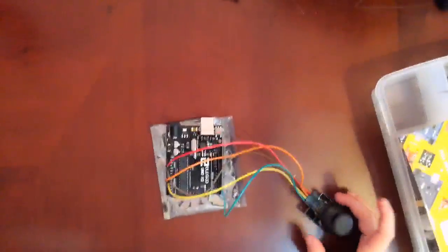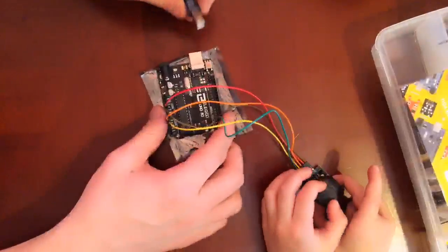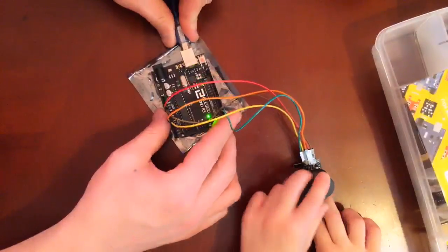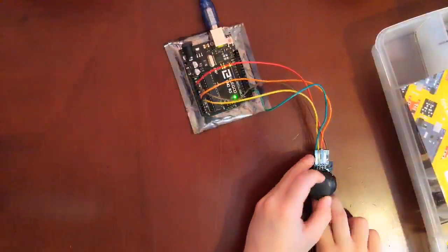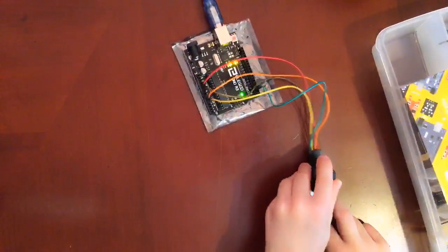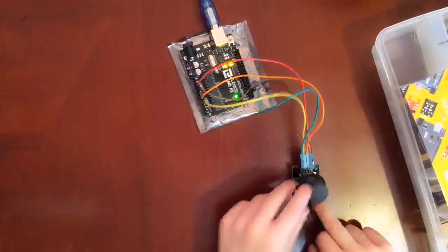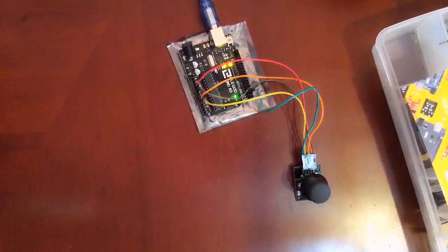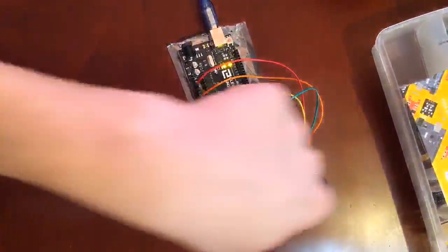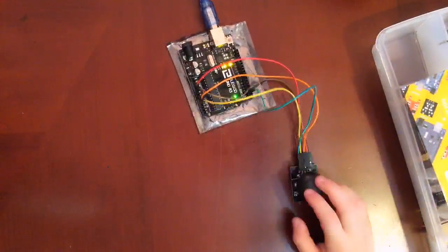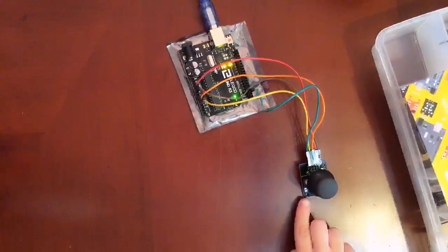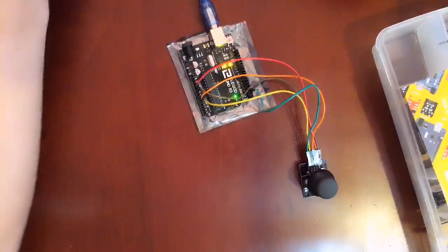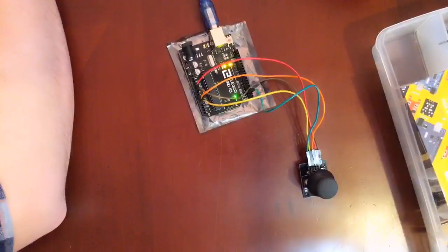So, let's go back over here. We'll get power to the board. Alright. So it says we need 5 connections to the joystick. The connections are key, Y, X, voltage, and ground. Y and X are analog and key is digital. If you don't need the switch, then you can only use 4 pins. We went with all 5, that's fine. Code, after wiring, please open program, upload the code.